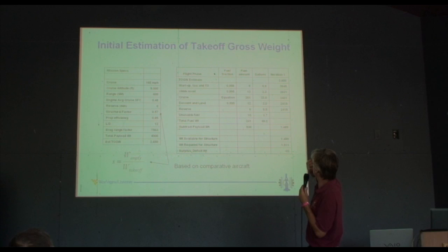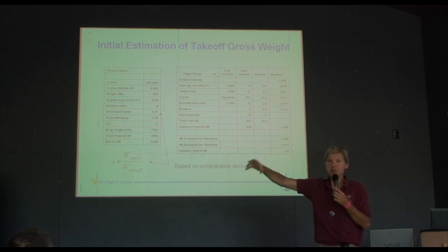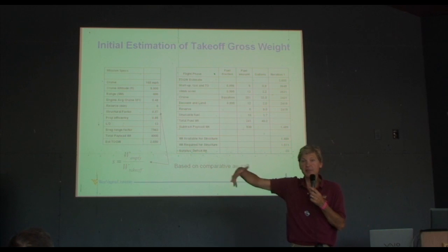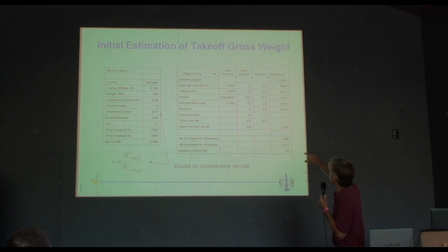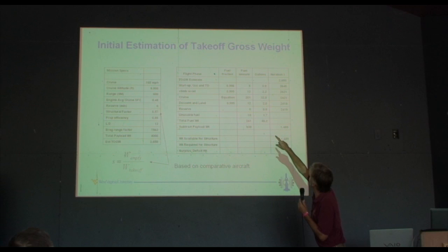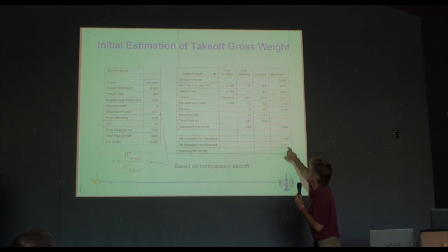And if you break down a typical mission profile, which you do when you have a lot more time and you're really working out the details, if you use the equations that I use, you can break down the fuel amount and the gallons of fuel for each segment of your profile and check that you do indeed have just enough fuel.